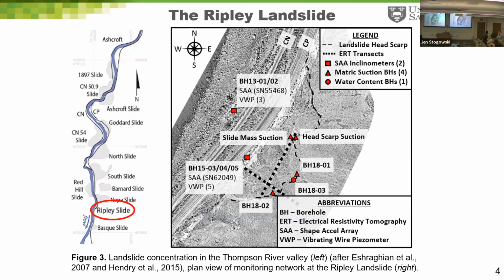A major factor in its stability is the seasonal changes in river level, which can vary by 8 meters throughout the year. The base of the Ripley Slide is directly exposed in the Thompson River, and historical explanations for the displacement have targeted the buttressing and drawdown effects caused by changing river elevation, artesian pressures underneath the landslide toe, erosion exposing geologic controls, and irrigation on the upper terraces.